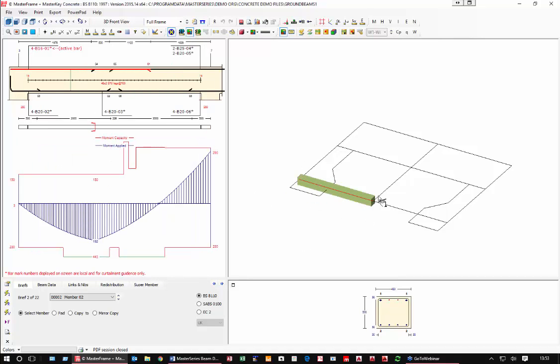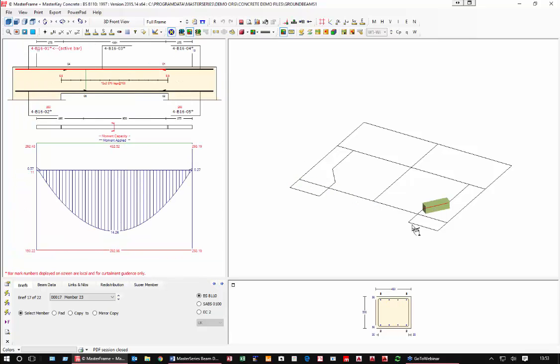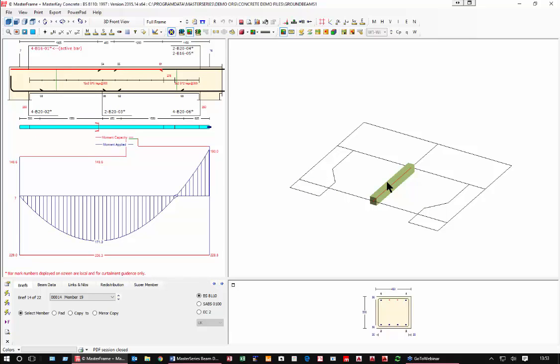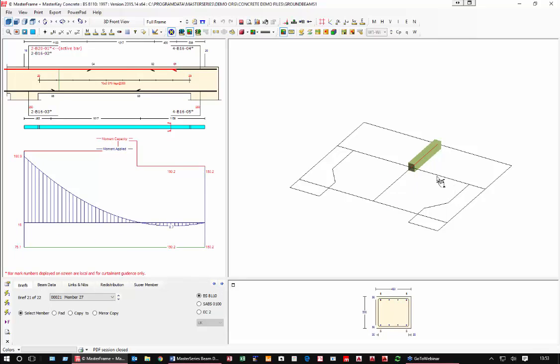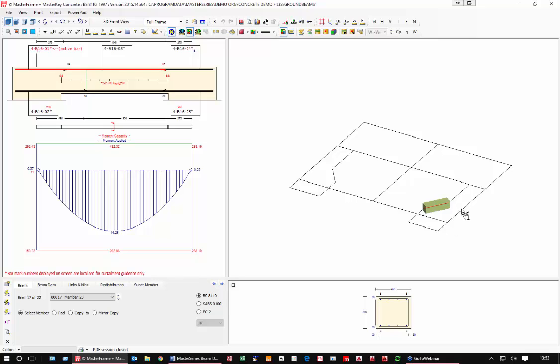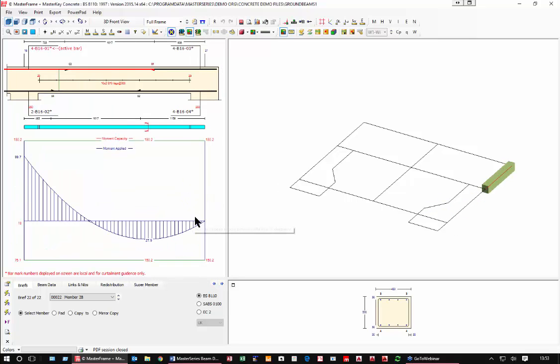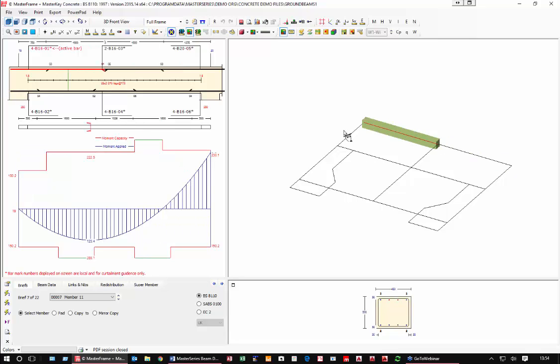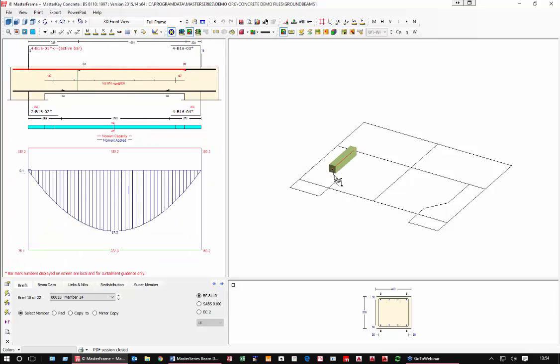We'll also see from time to time that we will have torsional design coming through. So we are going to have torsion in our beams when required, and not when we don't want them, because we can have these ends coming in pinned at the ends so we don't develop torsion around the corners. So very flexible, very, very simple design of grillages of concrete beams.